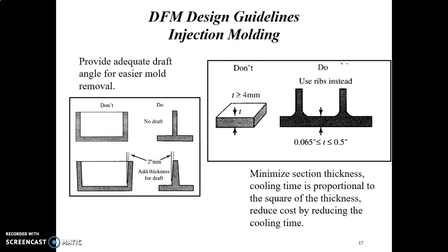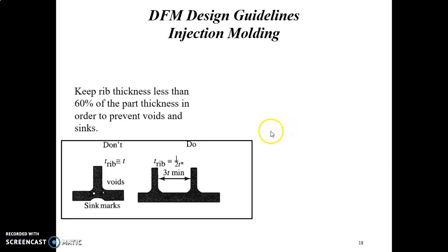So just remember to account for the required strength of your product wall and to adhere to best design practice for minimum wall thickness. Okay. So wall thickness will have a big effect on the cooling time. Next, we should